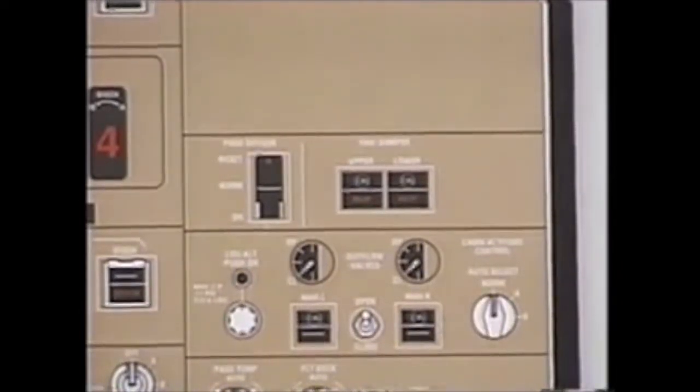Auto selector for cabin altitude control in normal, again, allows the system to alternate between controllers on each subsequent flight, or allows you to select the appropriate A or B controller. Regardless of the switch position used, if the selected controller fails, the other controller will automatically step in. Immediate action for a pressurization problem, which will result in a cabin climbing above 10,000 feet, is oxygen mask on at 100%, crew communications established, call for the QRC.